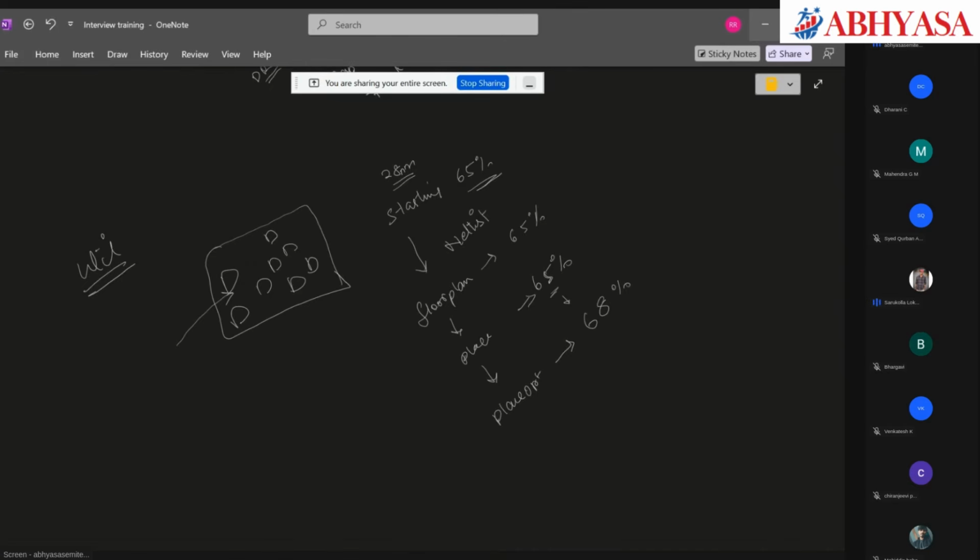Here we are placing standard cells, sir. Whatever is outside, I'm placing inside. It means in place stage, overlaps will happen, sir. Legalization of overlaps will happen. So standard cells will be placed somewhat far from each other. Okay, the core area.